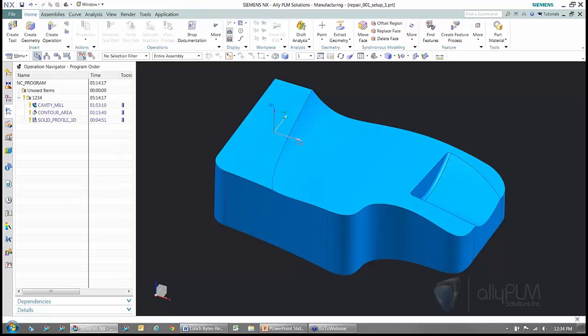The process for the repair will be to weld the gouged area and then remachine it back to the correct shape. So the first thing we need to do is decide how much weld will need to be placed on the part. To do this, we'll change the length of the cutter to 95 millimeters inside of NX to simulate what actually happened out on the machine.